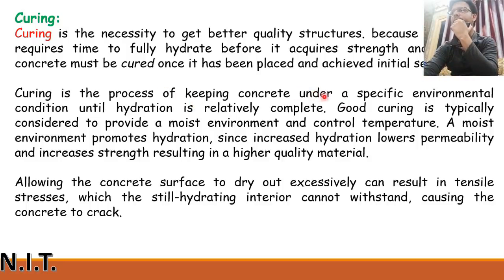Curing is a process of keeping concrete under a specific environmental condition until hydration is relatively complete. When the hydration is completed, you can remove that specific environmental condition. Good curing is typically considered to provide a moist environment and controlled temperature.